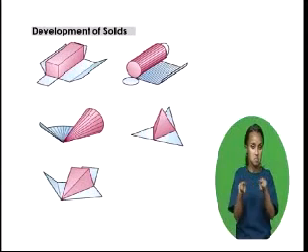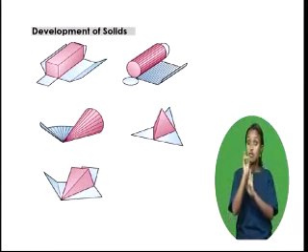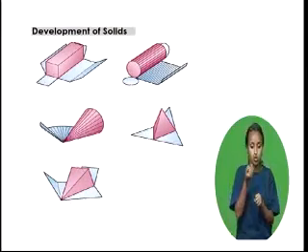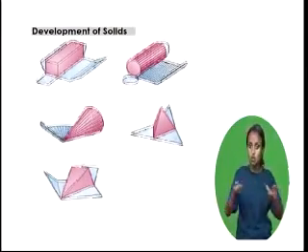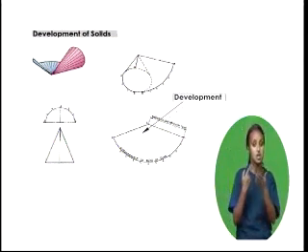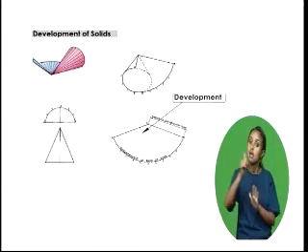Well, students, do you know how real objects with the shape of a cube or cone can be constructed with a model paper? Next, we will answer this and similar questions. A development is the unfolded or unrolled flat or plane figure of a three-dimensional object. When surfaces of an object are laid out on a plane, the drawing obtained is called its development. The layout is full size and made on a single flat plane.